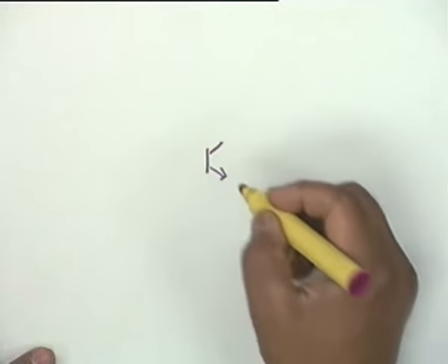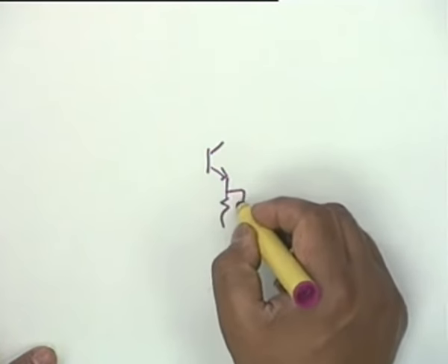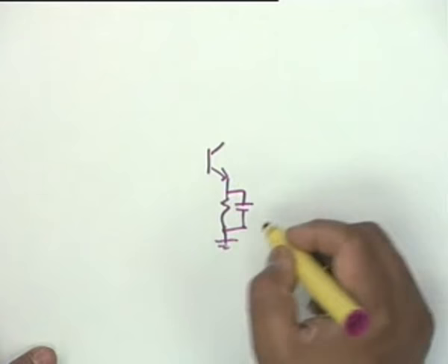Or you could also do this, that use 2 tuned circuits tuned at the same frequency, one at the input of the amplifier and the other at the output of the amplifier. You can do that. Let us see what this circuit looks like. Is the point clear? You may not use two amplifiers, you may use the same active device, but a tuned circuit at the input and a tuned circuit at the output. Let us see what this circuit looks like and what is its problem. I am going to draw now a typical RF amplifier circuit and then I shall discuss what the problems are.